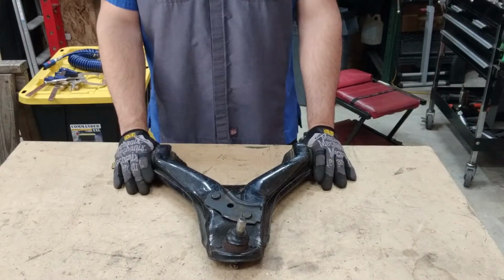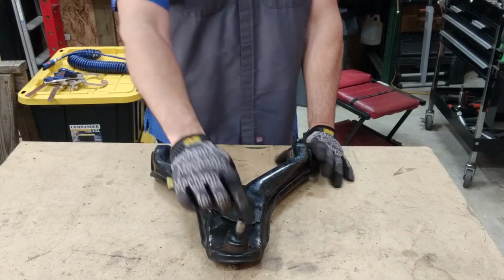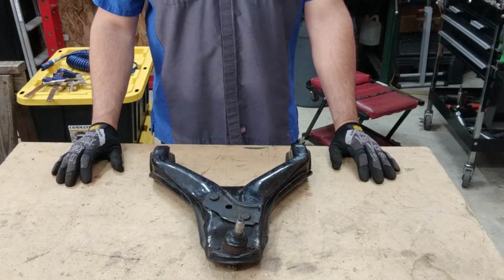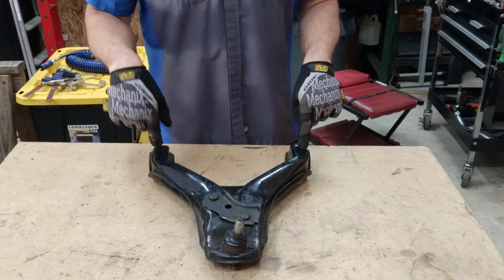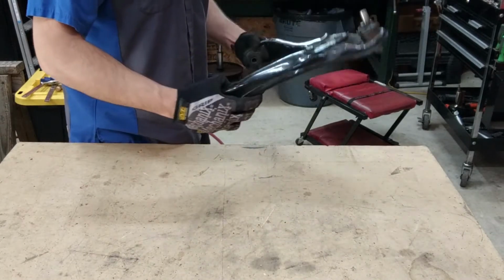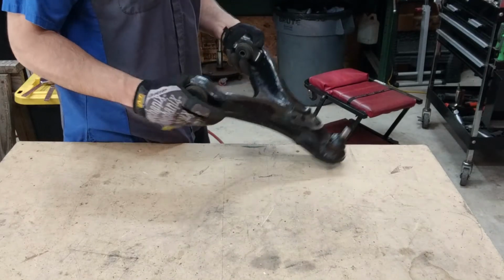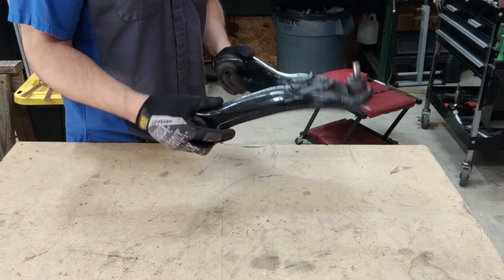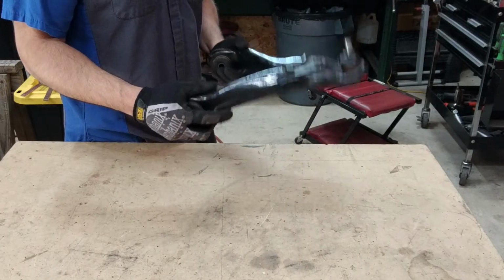When we're talking about control arms with ball joints, there were some control arms that had 3 points of contact, 2 at the chassis and 1 at the ball joint. The ones at the chassis are designed to allow pivoting across the bushings, torque with vehicle weight, and allow that suspension component to travel up and down.